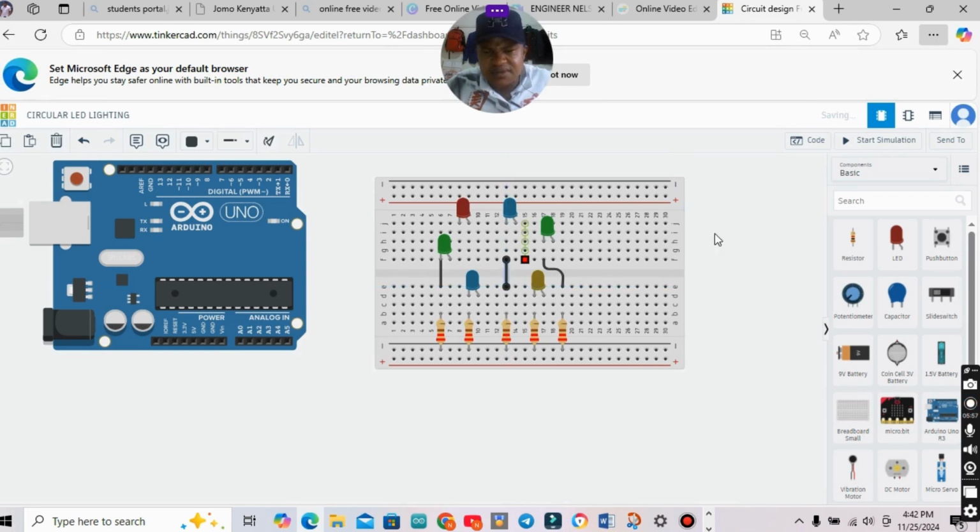Then the last one is the first LED, the red LED. So it is there. I bridge that gap. So we have already supplied our cathodes with the resistors and I connect them to the ground of my breadboard. So the next step is the powering. I can serve my breadboard with the neutral or the ground. So that is the ground. We have connected the ground there.